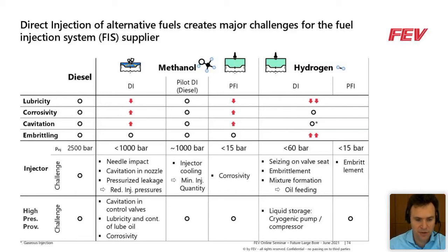Lubricity will also pose a problem, so we will have to consider also lubricating oil and also corrosivity of the methanol. So this is also a corrosive material. But while in the hydrogen case, if we consider a liquid storage, we have to deal with the cryogenic systems with all the issues that they concern, let's say.